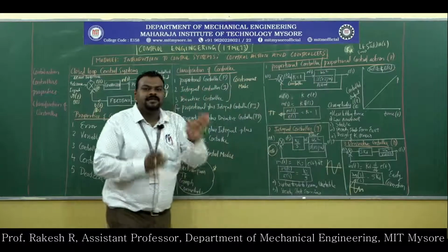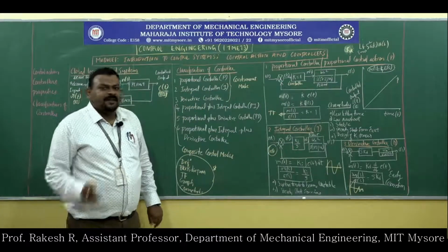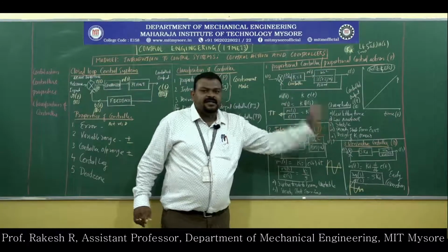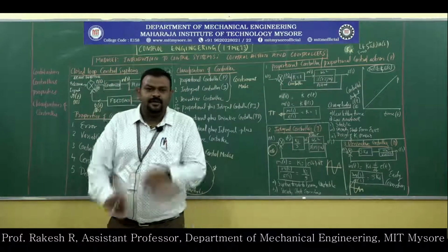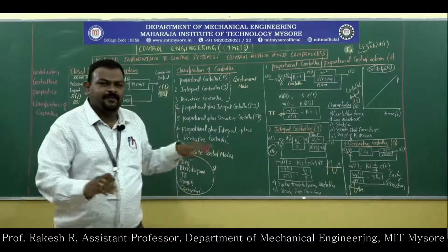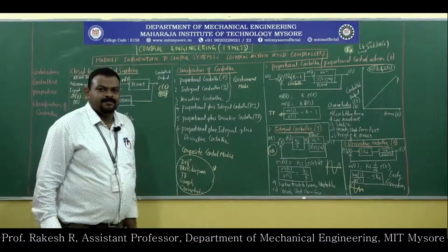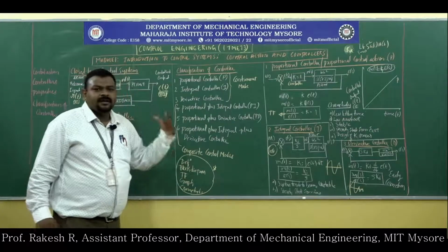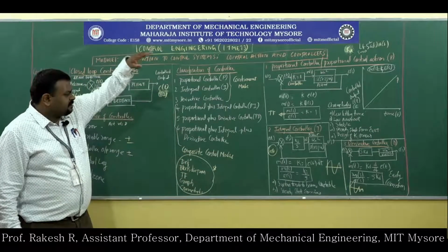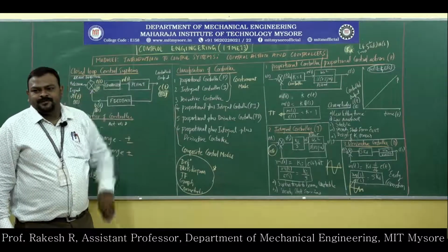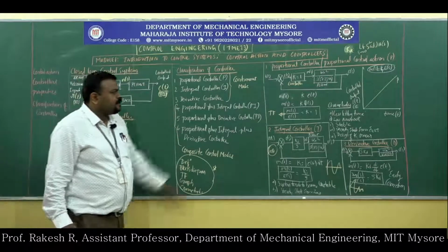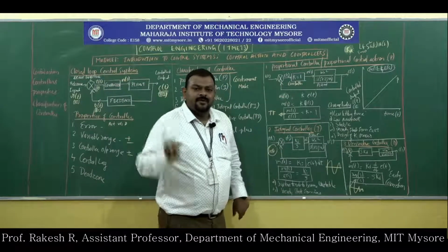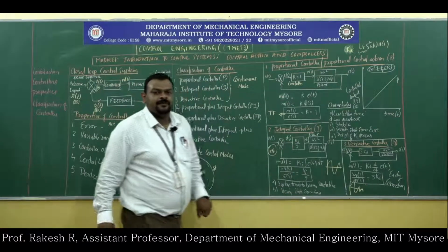It should be used in combinations. Either it should be used in proportional and integral or proportional plus derivative. If we use them in combination, the response of the system will be stable. So this is one of the important things in control action. So these are continuous modes. In all the cases, the response of the systems will be varying with respect to time.